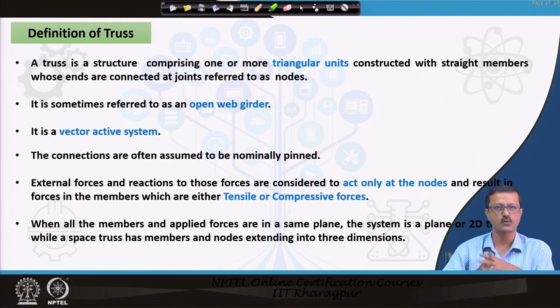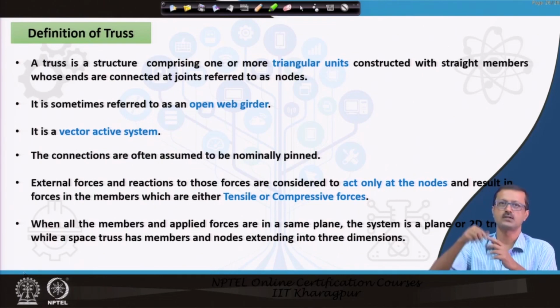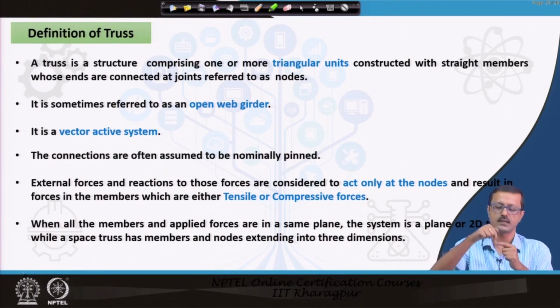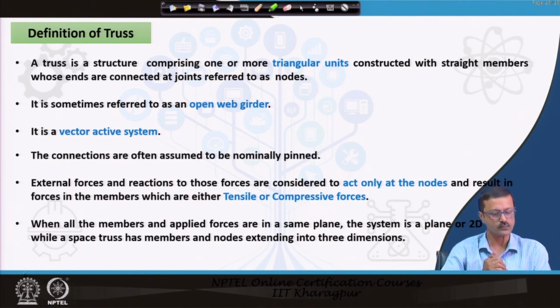So, this last but one point is very important while analyzing any kind of truss: the loads are on the nodes, and the components of the forces in the members are either tensile or compressive, when all the forces are applied in the same plane of the truss.